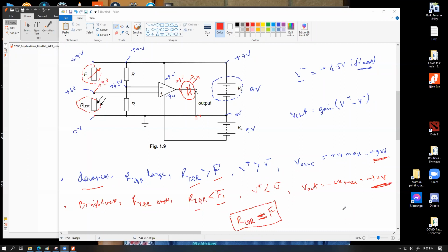For example, in cases where we are dealing with a very high amount of heat, and we really don't want to rely on the flaky behavior of electronics. You have to understand one thing: a bimetallic strip is a robust thing that will do the job. An electronic sensor is a precise and sensitive device that will accomplish the job.